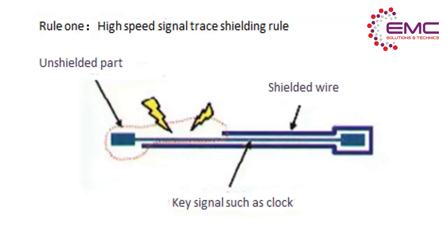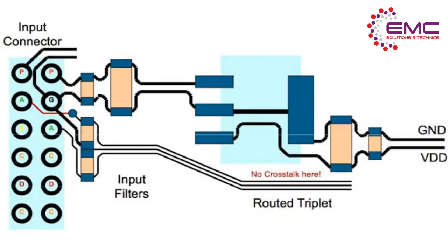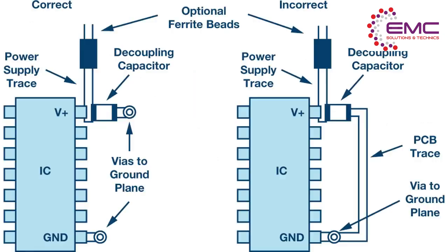Analog circuits. Traces carrying analog signals should be kept away from high-speed or switching signals and must always be guarded with a ground trace. A low-pass filter should always be used to get rid of high-frequency noise coupled from surrounding traces. In addition, it is important that the ground plane of analog and digital subsystems not be shared.